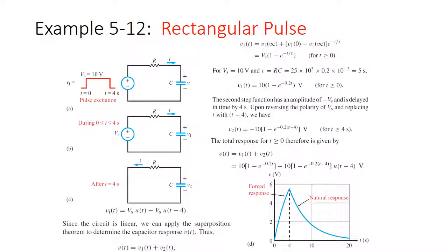And so for any time before t equals 0, that's going to be 0 because, again, there's no pulse coming in. There's no DC voltage. It's like having the battery unplugged. Nothing's going to happen. You're not going to get to charge a circuit with no battery. So as soon as you hit that 0, though, you're going to get that pulse function come out. And that's going to give you a pulse of a certain voltage for a certain period of time, which is exactly like what we just did in the previous one. We switched the switch on and let it charge up. It was like there was a battery there. And then we switched it off again and let it discharge because then there's no battery there.